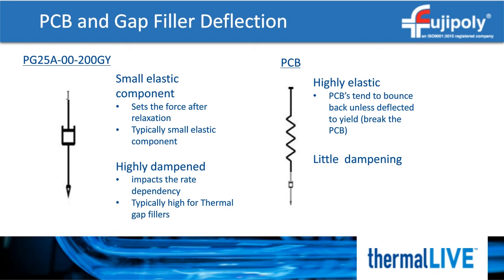The PCB, on the other hand, is almost all elastic, at least as far as we're concerned. The rate of compression will not have an impact on the stress created. This doesn't mean that it is 100% elastic, but we can say at the speed that we're working at and we're assembling at, and there is no oscillation, this can be ignored. If we want to know how the PCB would react under very high vibration, we would certainly want to know what that is.